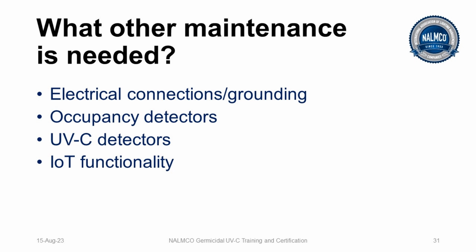So if you turn the lamp off, does that detector sense that the UV is off? Based on your witness point, let's say you're at 60%. So it's well below the 70% that we generally use for changing out a UVC lamp. What do you do? Well, if the UVC detector in the unit did not identify that as an issue, then that detector obviously failed.